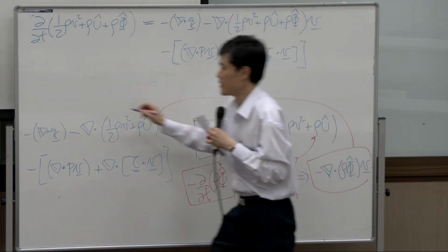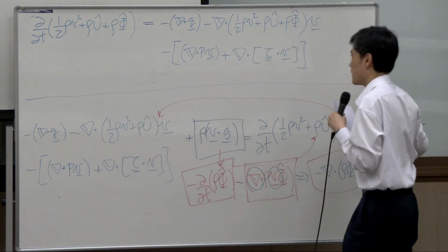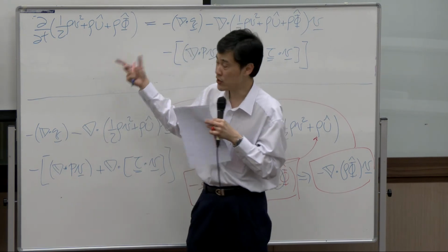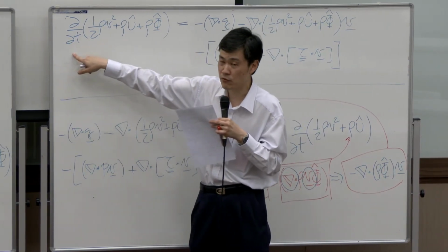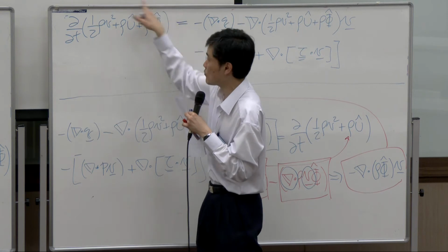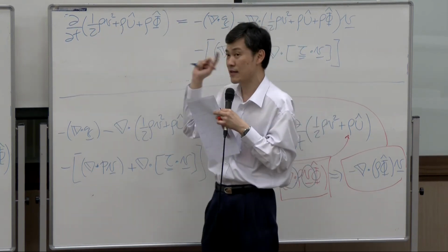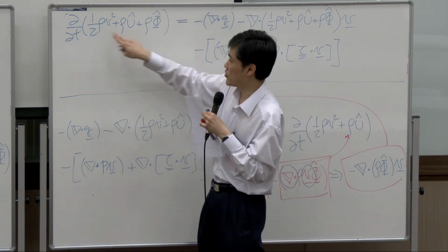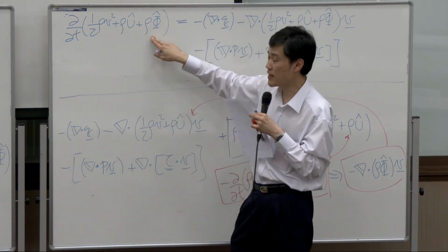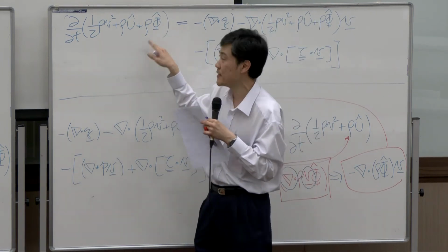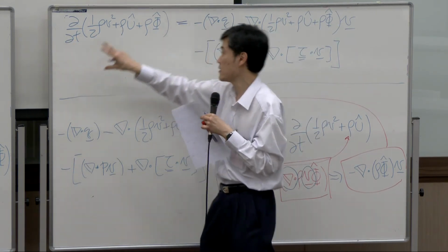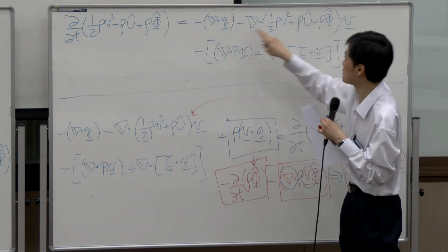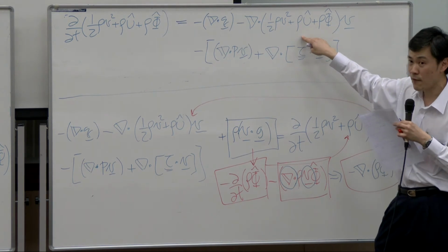If you look at this final equation, you see that this seems to be accumulation because it is a differential with respect to time. So this is the change of total energy within the system, and this energy can be divided into three parts: kinetic energy, internal energy, and potential energy accumulated into the system, just like what we learned in thermodynamics, equal to whatever is transferred into the system by means of conduction and convection, and convection follows the mass.